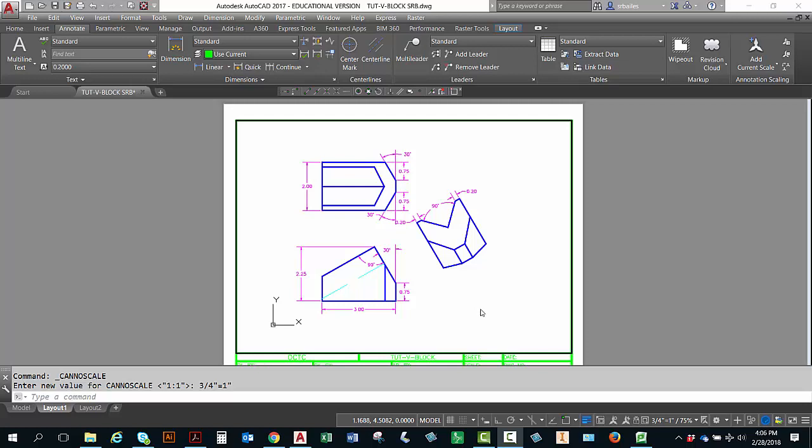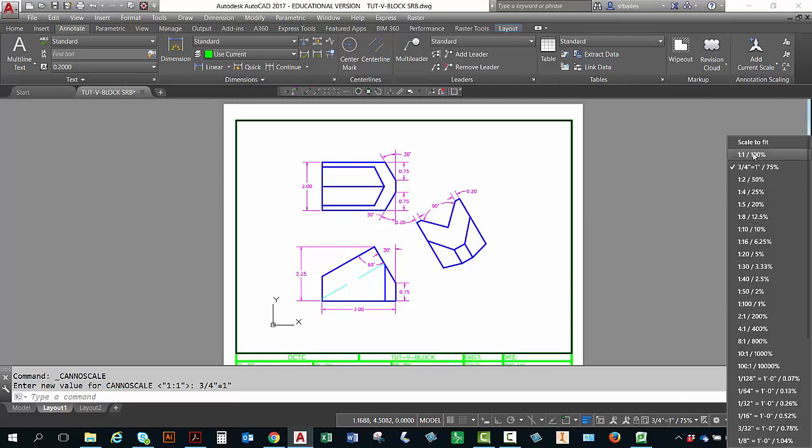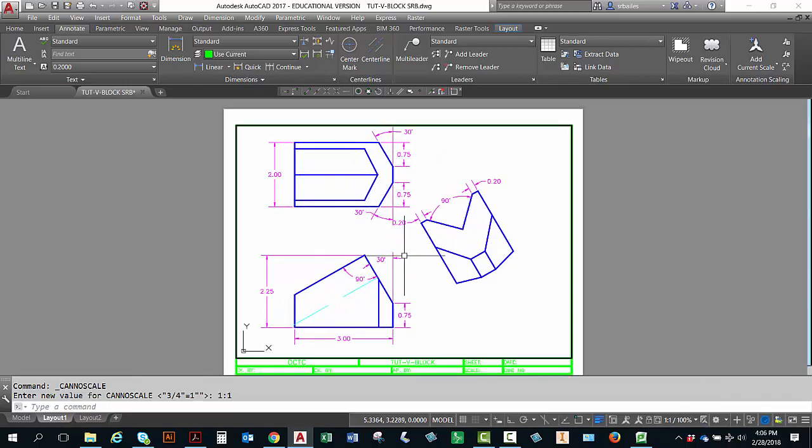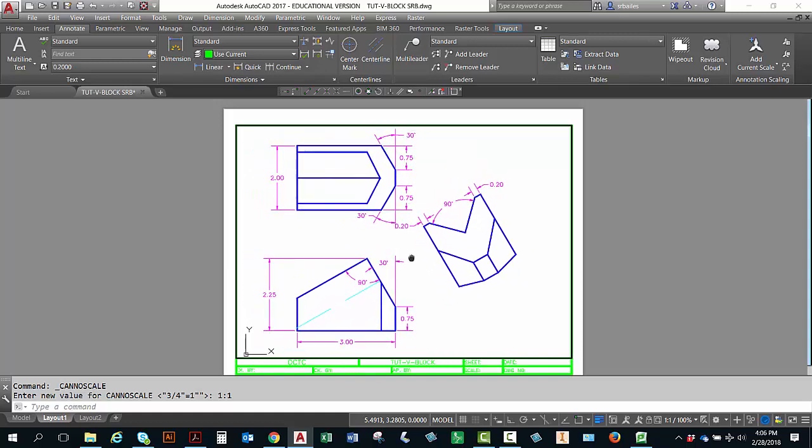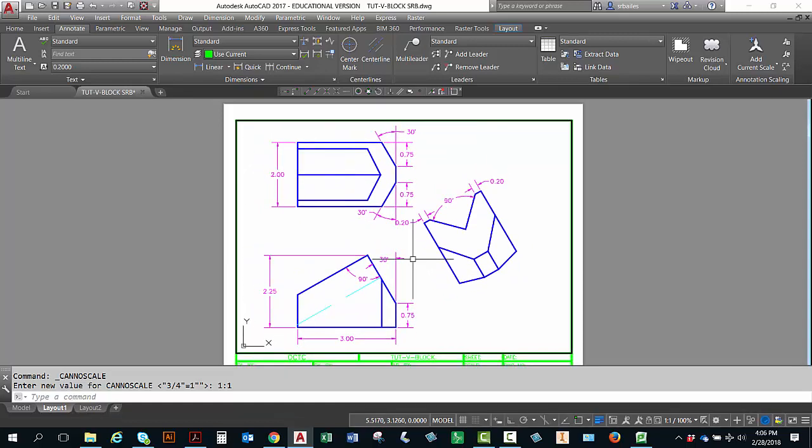Well, to make the viewport in the drawing adhere to drafting standards, that's what you would do to set the custom scale. This will work, as you may have seen, as a full scale drawing, properly positioned. Pan the drawing around by pressing on your wheel and getting it in position. So it will work and fit as a full scale drawing.